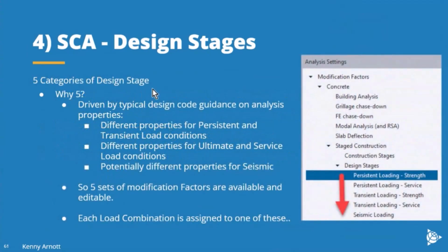So in TSD, in the analysis settings, in the modification factors section, we have stage construction. We've got the design stages, 5 categories here. We've got persistent loading, strength and service variations, transient loading, strength and service variations, and seismic loading. So seismic loading is pretty obvious. Transient loading would be something like a combination including wind, and a persistent loading case would be a combination that includes only gravity loads.